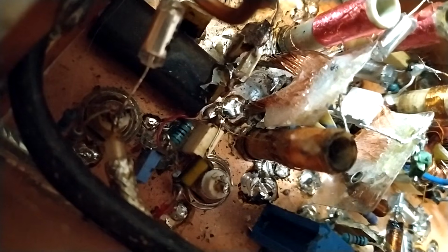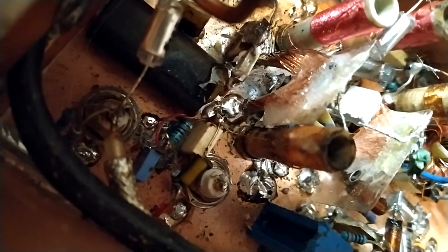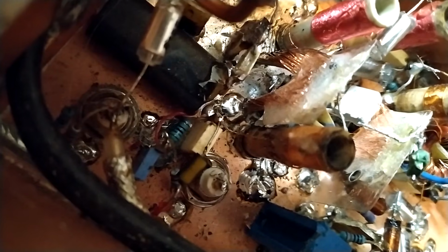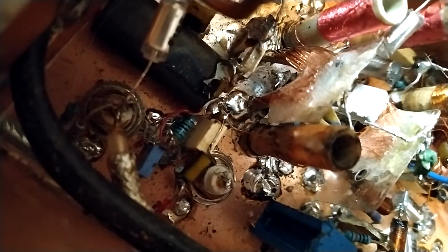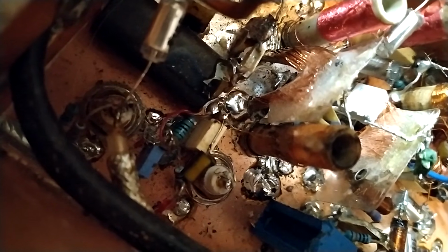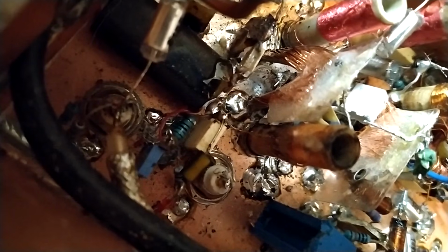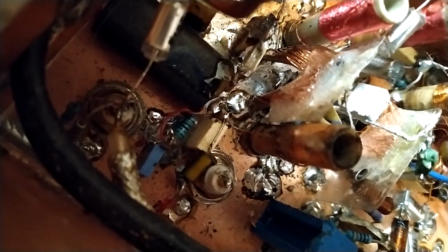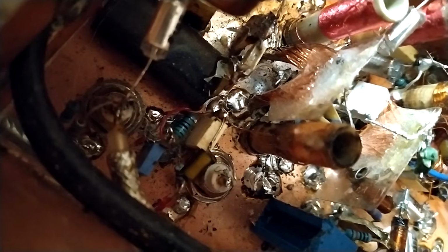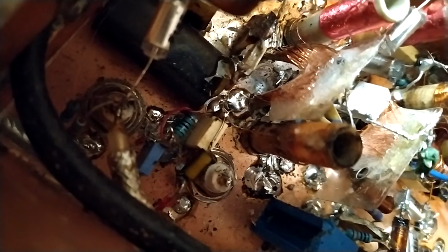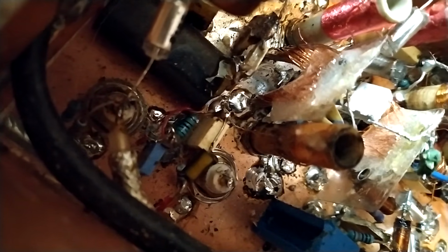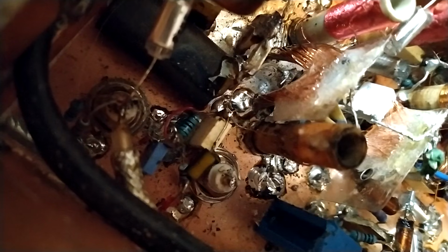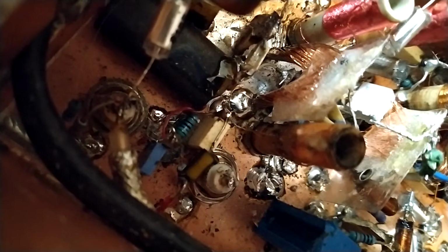I have glued a sheet of mica to the source resistors to get a good contact from the resistors to that sheet of mica. And then I have 2 wires, 3 square millimeters each, to the laminate up to that mica sheet, and glued from both sides with epoxy resin.